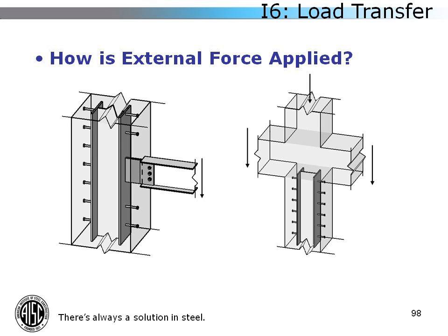On the left side of the screen, you have an encased column with a steel plate sticking out beyond, an extended tab plate. So this force is coming in through the tab plate. You could probably say that all of this force is coming into the steel section only. Conversely, on the right side of the screen is a composite column where almost all of the force is coming in from concrete beams and columns above. So you can say that all of it is coming in through the concrete.